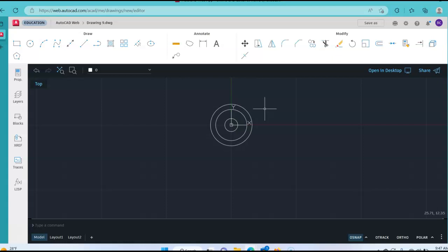But for right now, we need to add the other circle at the bottom. If we look at and read the print, we see that from here, the center of the other circle is somewhere down here in quadrant 3. So our points will be in the X minus 10 and in the Y minus 40. So I've got to establish the center coordinate point on that first.